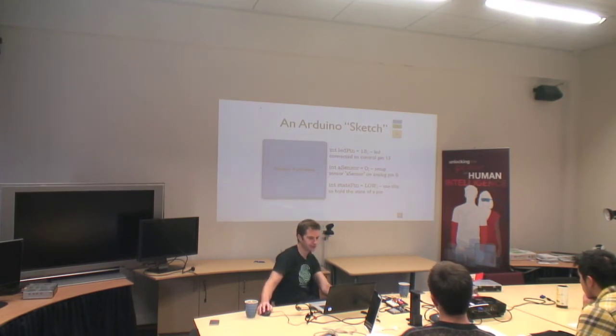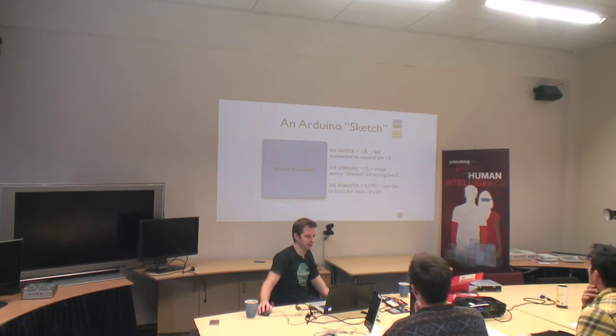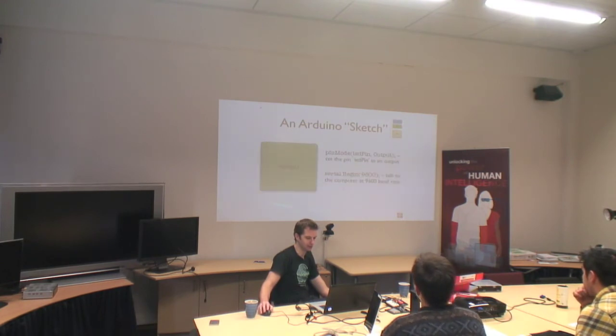So yeah, the LED pin is 13. All these sorts of things you might see in global variables. Set the pin to 13. Set up an analog sensor on analog pin 0. Set the current state of the pin to low, whatever. Set pin mode to LED pin output.